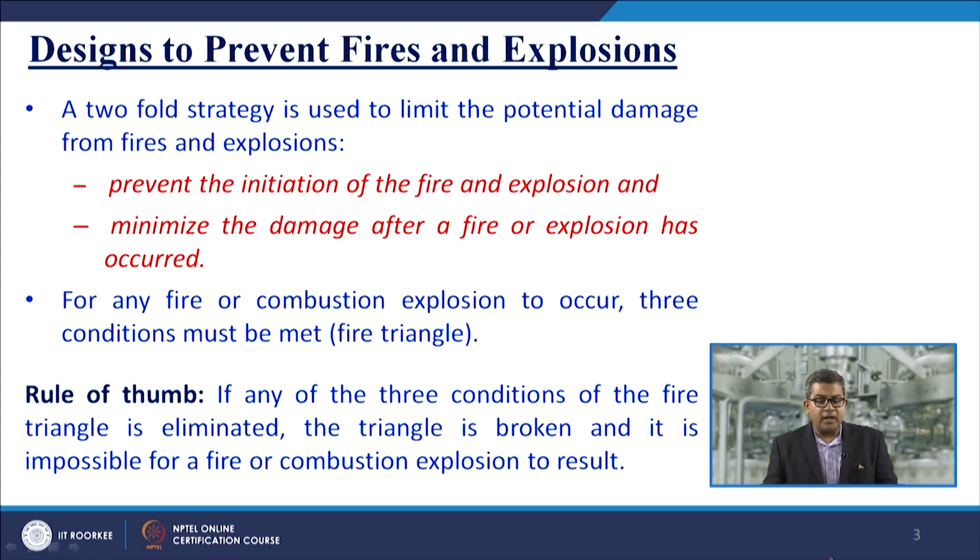For any fire or combustion explosion to occur, three conditions must be met. Please recall the fire triangle: fuel, source of ignition and supply of oxygen. And to sustain the fire, a net chemical reaction, which in this case is combustion. So if we wish to make the system safer and if we cannot avoid the generation of fire, then we must design the system accordingly.